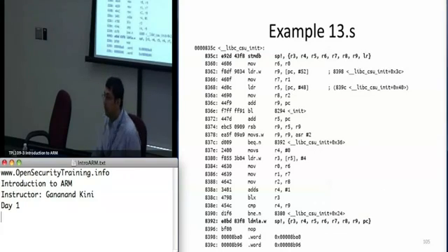Application 8362, that wide load, that one. What value does PC have there? Is it the current instruction plus 4 or plus 8? Because you've got a wide instruction followed by 2 narrows. Yeah, so the wide is actually for this instruction itself. So it's saying the instruction is encoded in 32 bits. Right. And all it's saying is take the value of PC. I'm wondering what is the value of PC at that? So it's going to be pointing to this guy.